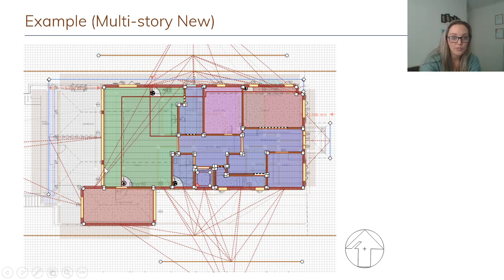These yellow stripes around the building are the windows. This house has got double glazing. The yellow indicates double glazing, the blue indicates single glazing, and all of these dotted lines and solid lines here indicate neighbouring buildings. So I was mentioning before, we model all of the shading factors. These blue lines here are eaves and pergolas and alfresco areas.